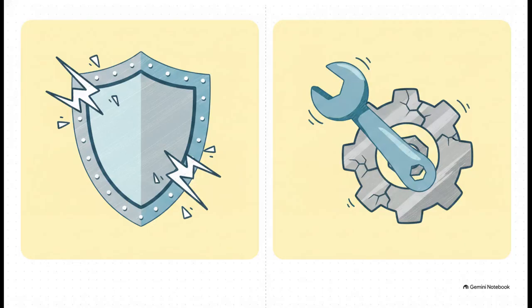Now, to manage those non-conformances, you're going to rely on two vital actions. First, preventative actions. As the name suggests, these are implemented before non-conformances even happen, sort of anticipating the error. Then you have corrective actions, which are implemented after an issue has been identified in order to fix it. Actually, you don't just pick one. A top-tier site manager actively uses both dynamically. You want to prevent the occurrence in the first place, and if something slips through, you ensure the non-recurrence of that issue. That's how you guarantee the client gets a premium final product.